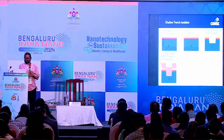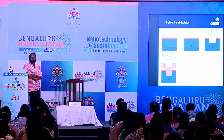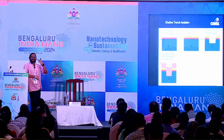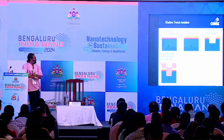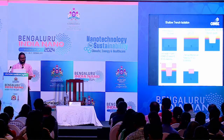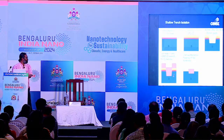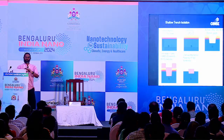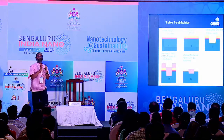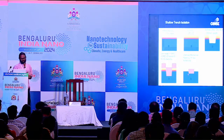You throw in the TEOS, tetraethyl orthosilicate, that will react in the plasma, and then you will get silicon dioxide. And then what we do is we remove whatever excess material that we don't want, okay? And only silicon dioxide is kept, and this will create an isolation. And this is what we call isolation oxide.